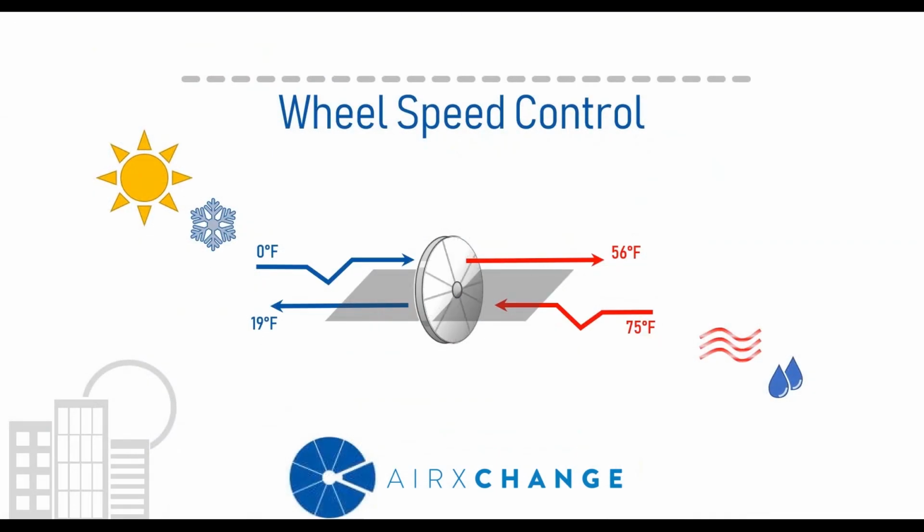Okay, the next method that we're going to talk about briefly is wheel speed control. Wheel speed control is another very popular method to mitigate frost. With wheel speed control, the premise is to slow the wheel down to warm the core temperature. By slowing the wheel down, you're also minimizing the wheel's ability to transfer heat and humidity.